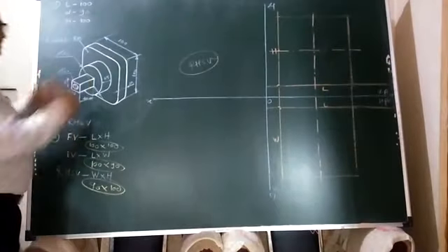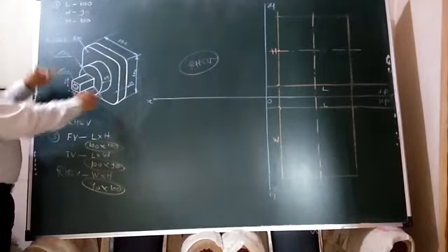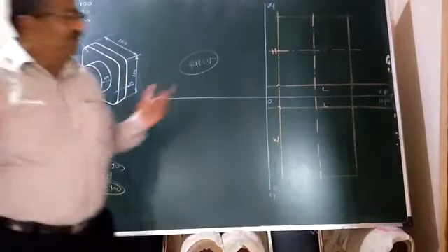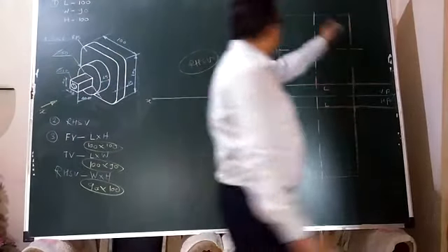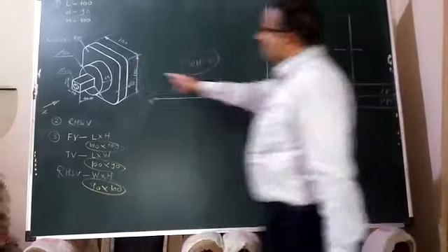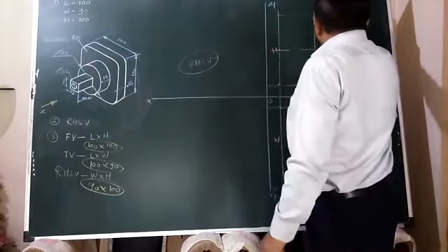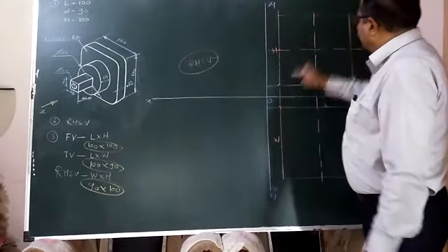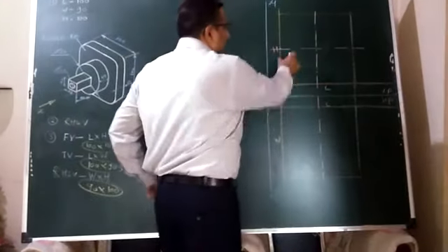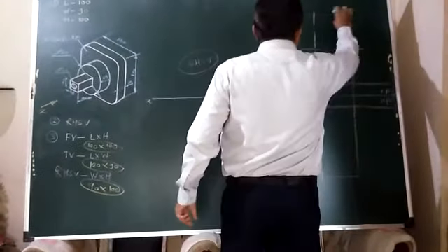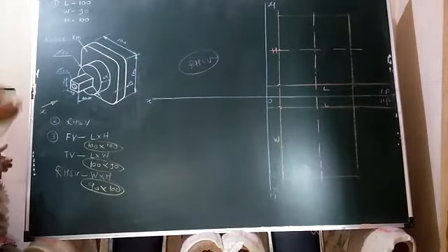See now, at a glance what will appear in the direction of X? This biggest, largest plate, which is on the right extreme end of this object, will appear, that is 100 by 100. But are all the corners sharp? No. All 4 corners are chamfered ones. A 15 mm radius will be provided at these corners. That too, as I just told you, by the geometrical construction method of the parallel line method, we can get the corners cut with these quarter circular curvatures.